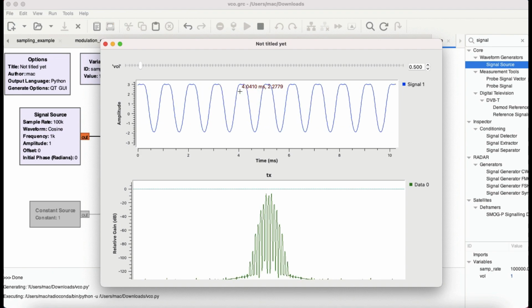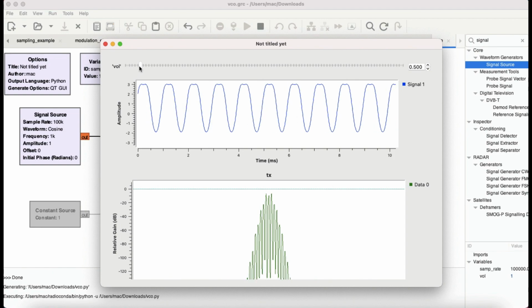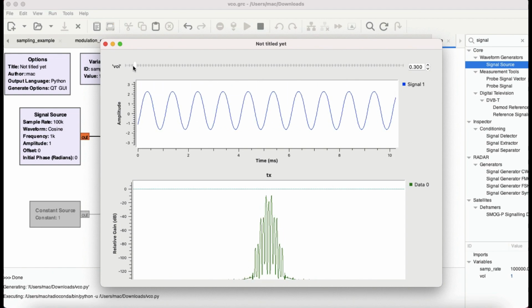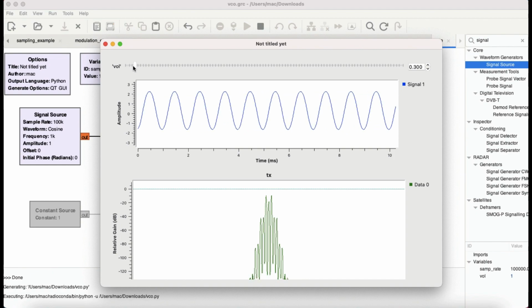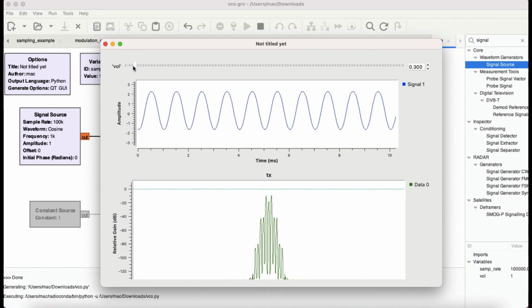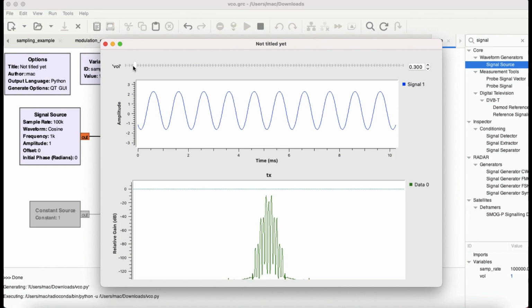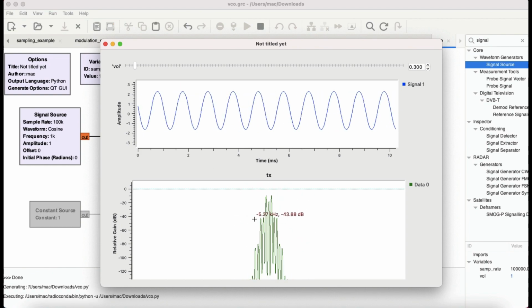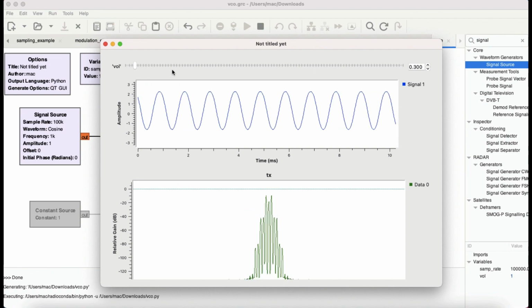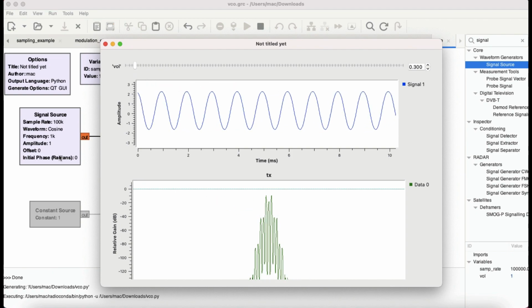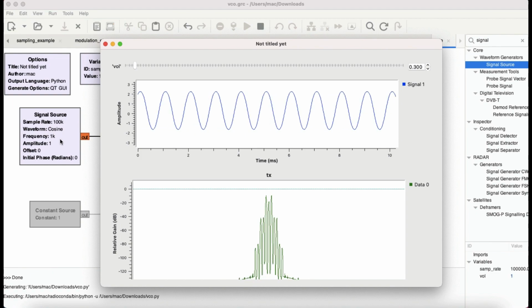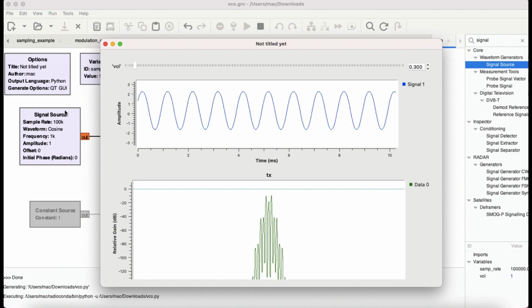Either you can control it with a constant source, just like I showed you before, and this is normally what we do in circuits as well. Or you can also use a sinusoidal source, and that sinusoid will automatically change the amplitude, and that's why you are seeing this spectrum, as compared to a constant value spectrum where the frequency was moving as I was increasing the voltage. But here it's done through your signal source, which has a sinusoidal signal of 1 kilohertz.